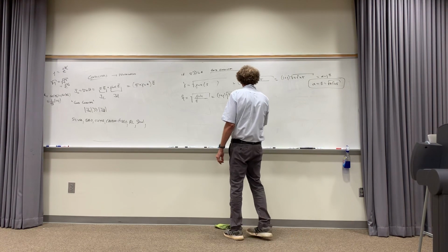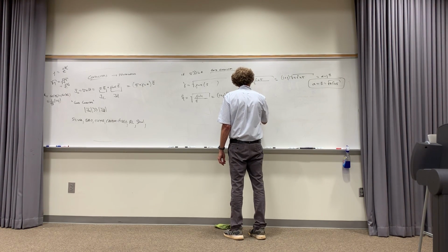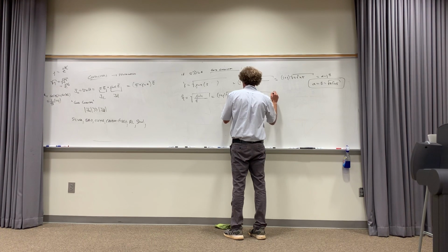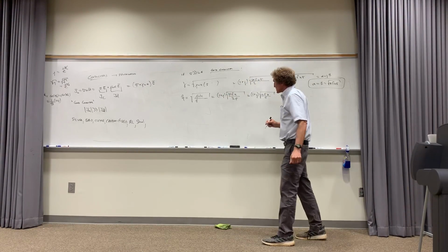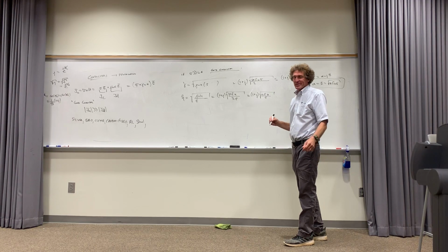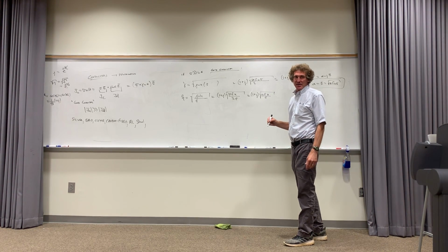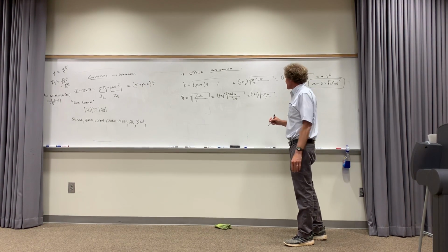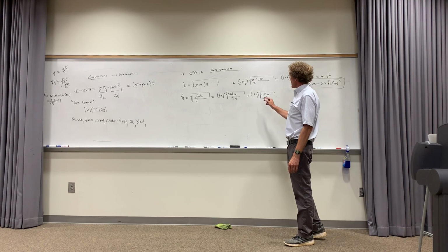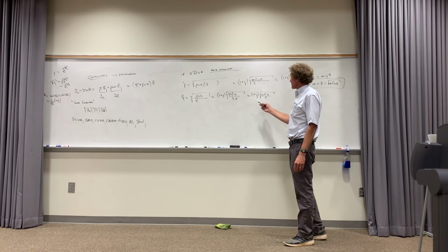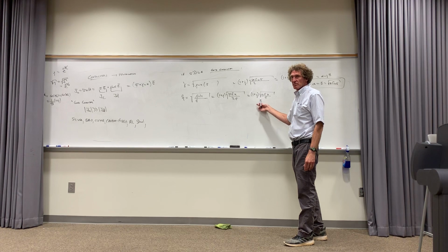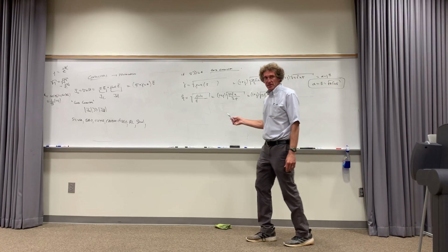Now what do you see happening? That means it's 1 plus j, right? And now I have the square root of pi f mu over sigma is equal to the intrinsic impedance. I'm going to say something else. Good luck if you want to try to kill that thing. I've tried before. Doesn't work. Anyway, when I have this, that means the real and imaginary parts of the intrinsic impedance are the same. Also means the angle of 45 degrees occurs there, right?